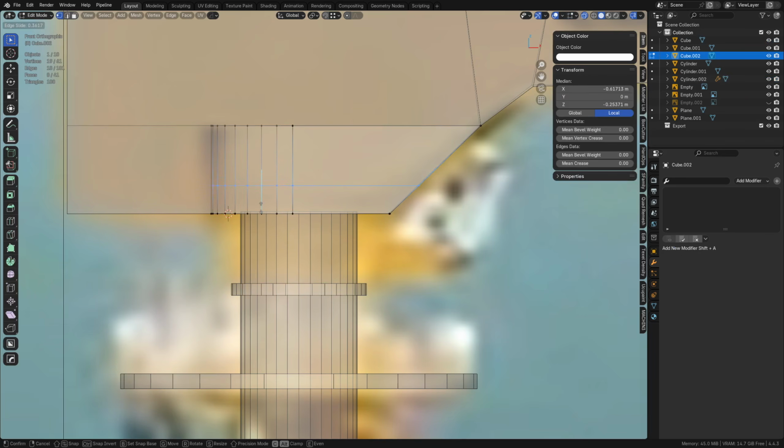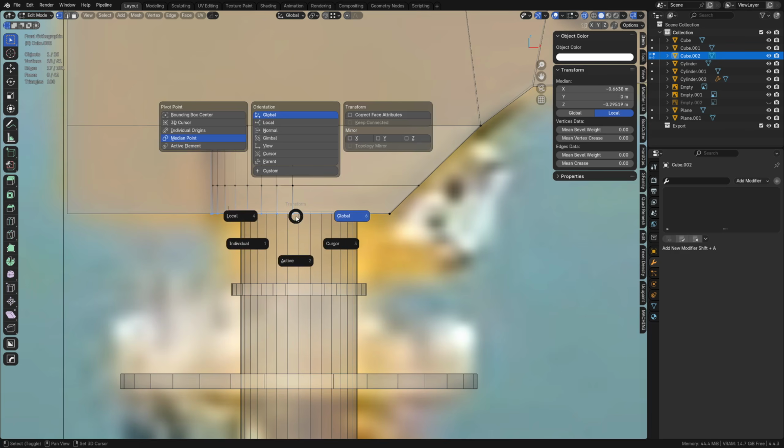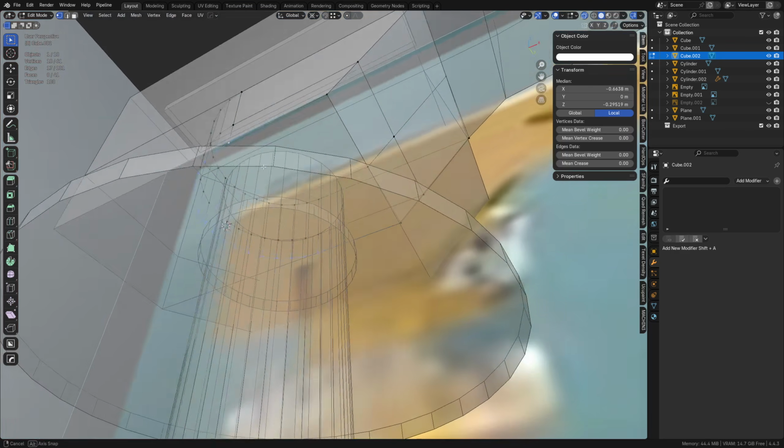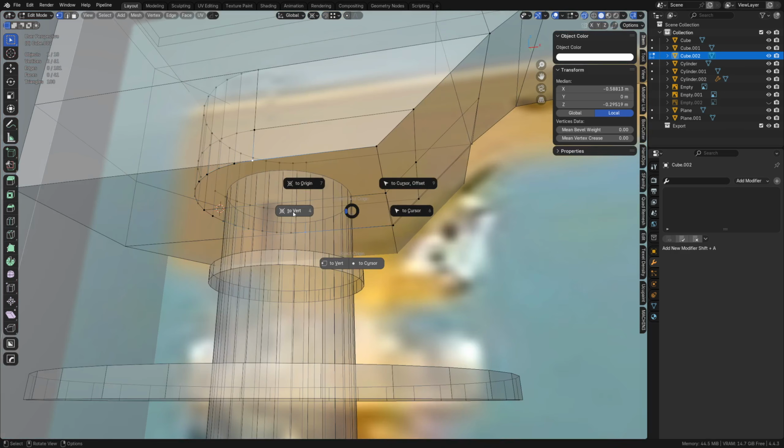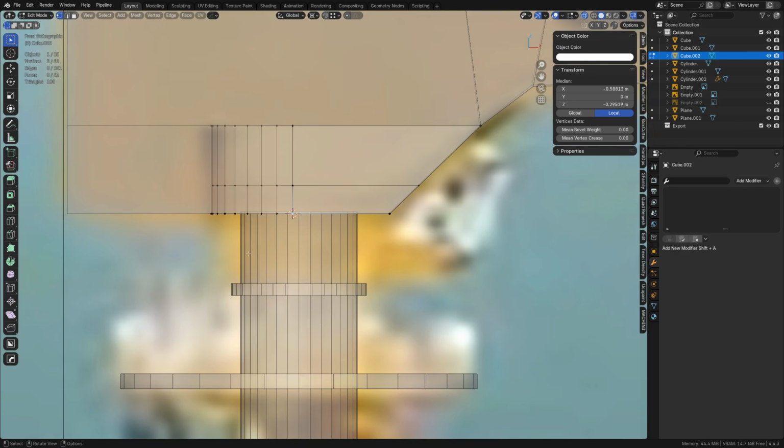And this is going to go about here. There's a loop cut maybe, and then this all shifts inwards. So I'm going to use the 3D cursor, right? We grab these two, Shift S, cursor to selected, and we use the 3D cursor as a pivot point. Now we can hit S and X in this case. We can bring it in maybe.